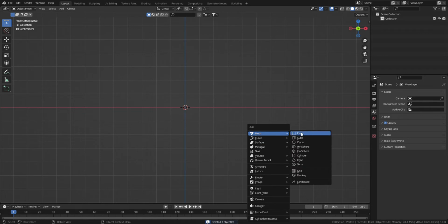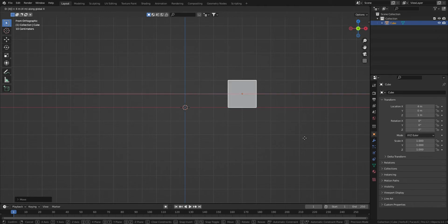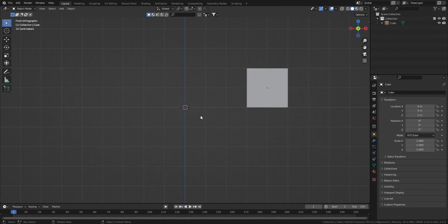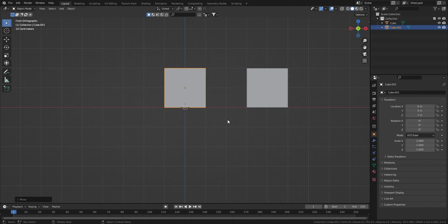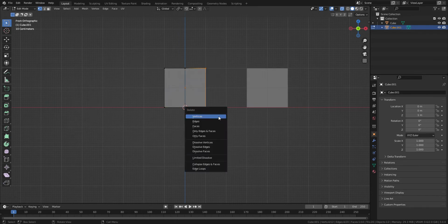Now we're going to make a cube for reference. This is a height reference, scaling reference, alright. And then we go back here, add a cube, G Z 1 brings it to the top, and then tab, and then what I'm going to do is add a loop cut, and then we're basically going to mirror it. If you've never done that, this is how it's done.